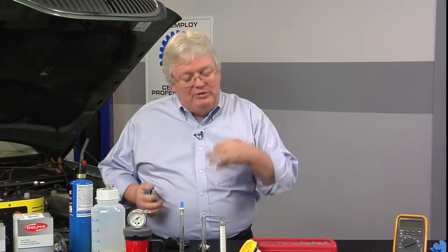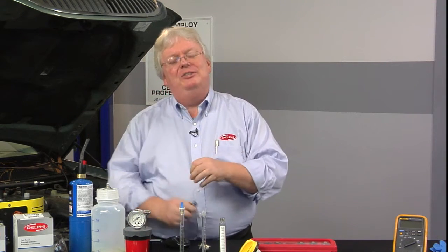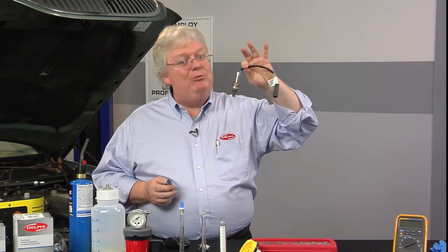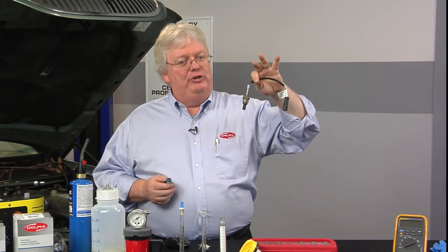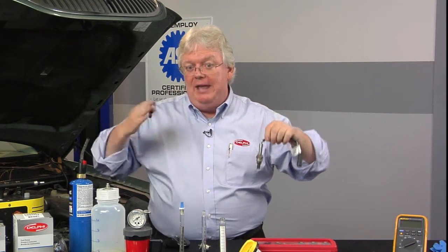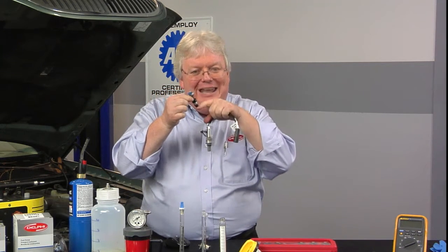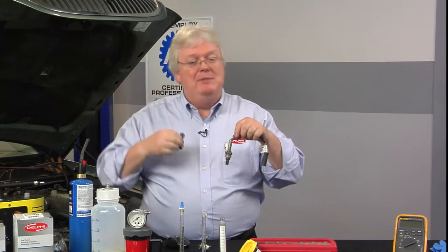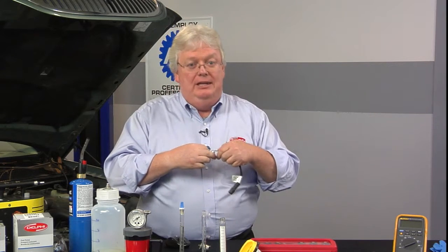Most systems, unless it's a very new car with what's called fuel trim imbalance, cylinder to cylinder imbalance, if you don't have that, and we look at the fuel trim as a whole on either the whole engine or one bank, the O2 sensor is going, boy, this is really rich on this bank. And so the trims keep going down and down and down, negative, negative, negative, until all the cylinders that didn't have the drippy injector, all but one, now run out of fuel, have maybe intermittent misfires and some really nasty looking ignition patterns.